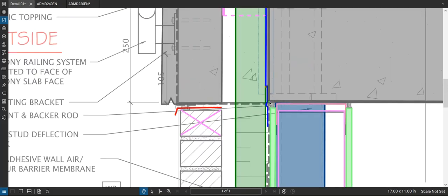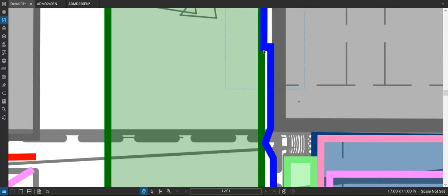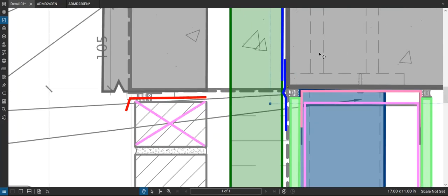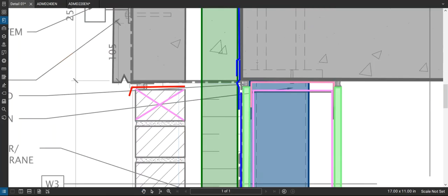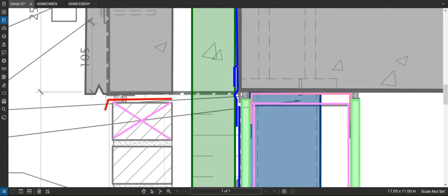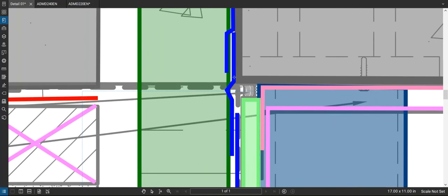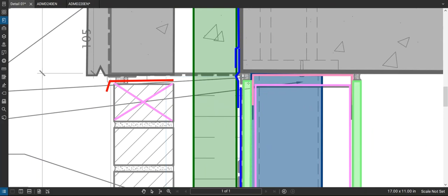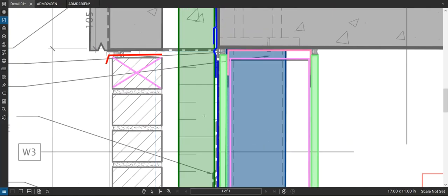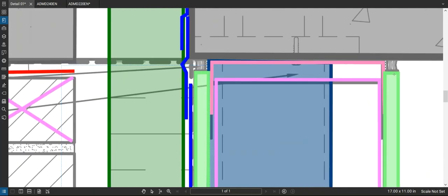At the deflection joint here, I've just shown a reinforcing layer to go in there. And then this one's going to overlap that one. Okay, like so. So I've done the positive overlaps at the deflection joint here. This strip right here would just be a little more flexible layer in case there was deflection there. Again, I think you'd have a pretty minimal situation here, but I've shown that. Oh, and by the way, you don't ever butt the gypsum board right up against the concrete. There's always a bit of a gap there, and then you can just put a sealant in there.